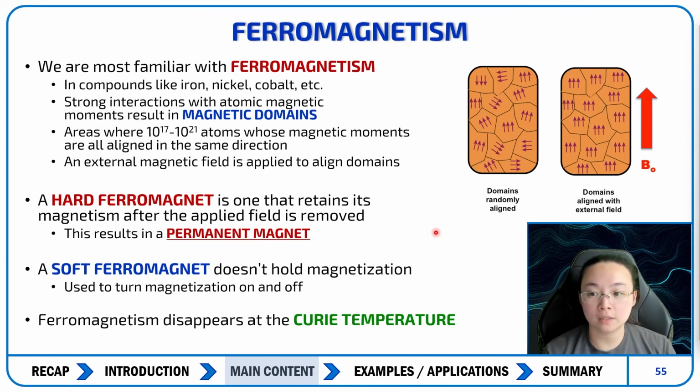And it's really important to know that this Curie temperature is the temperature where materials, in other words, lose their permanent magnetic properties. So they lose their hard ferromagnetism if they're a hard ferromagnet, but they may still be affected by induced magnetization. So that is fairly important because it doesn't mean that it can't be a magnet ever again. We can simply replace it by induced magnetism, which comes from current carrying wires or a current carrying object.